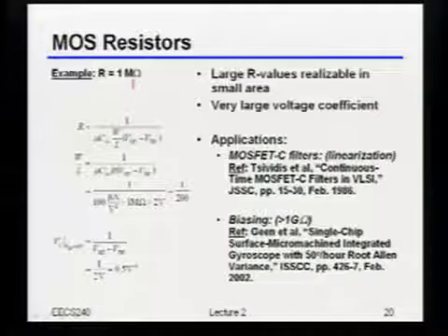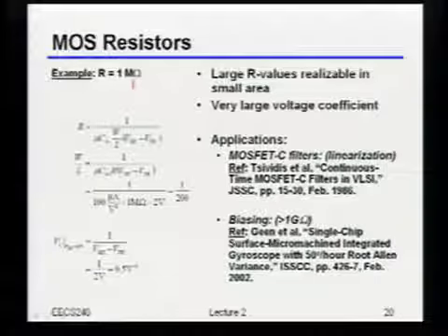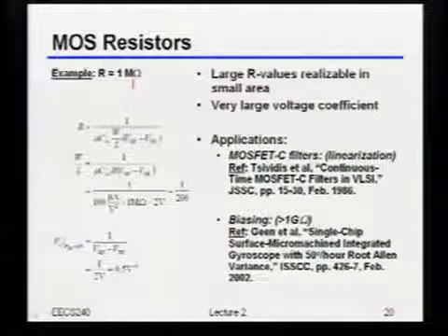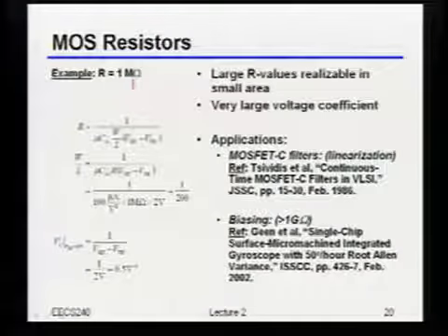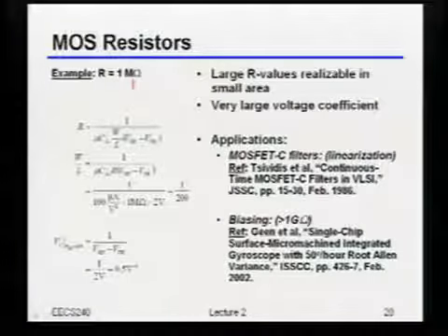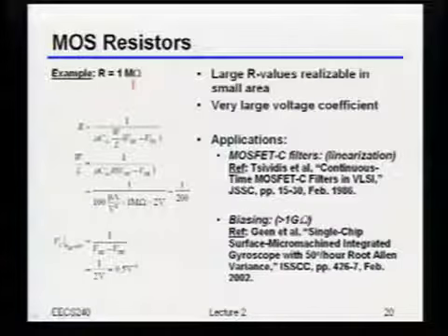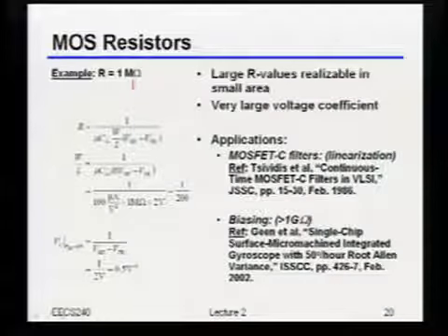If I have, let's say, a band gap or something that's generating some bias, where maybe I want a relatively precise voltage but I don't care all that much how much current is flowing through the thing, this might be okay. As long as I can tolerate the fact that the resistance varies, this might actually be okay. The other example that you also gave was a filter. Let's say I just want to make sure something is filtered enough.